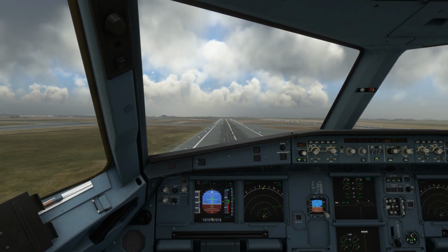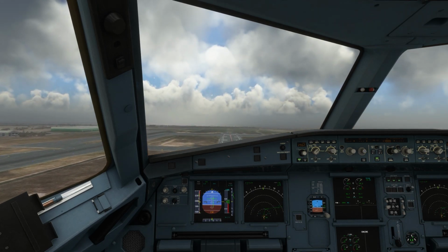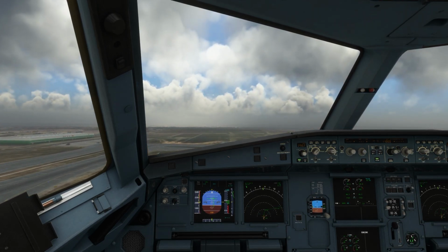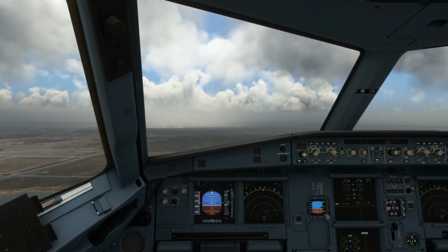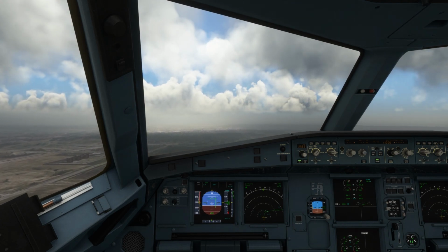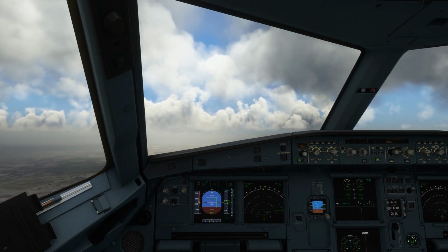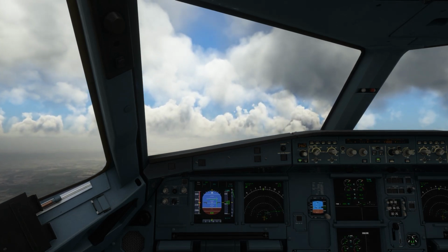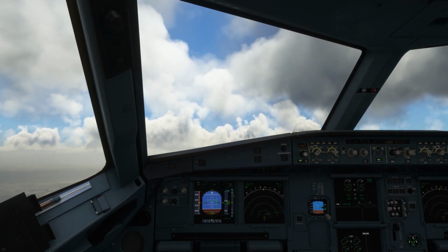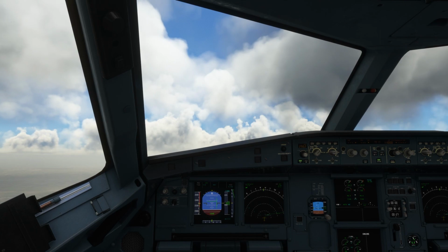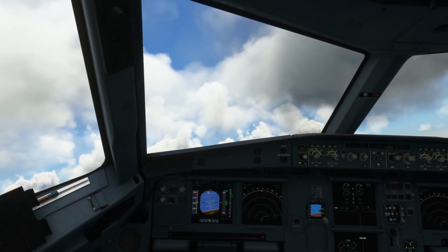Initially the climb is 10 degrees, and then I can increase the climb rate. As I have a positive climb rate, that's why I can take the gears up, and I can increase the vertical speed. As you can see that I was overspeeding. "All about departure on 119.65. Good day." Okay, 119.65. As I was overspeeding, that's why I've increased the vertical speed.